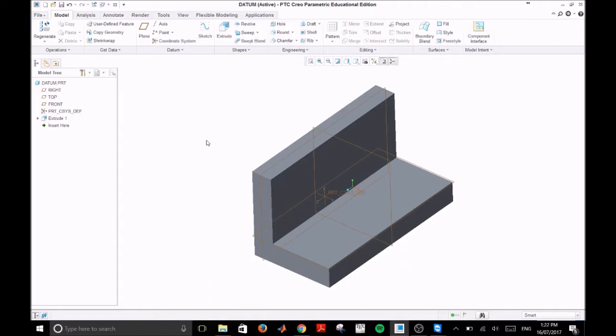By now, you've probably practiced a few extrusions and appreciate the usefulness of datum planes. For example, in this object, we have a right, a top, and a front datum plane, off which our feature has been extruded symmetrically. Symmetry is generally very good practice, and parts or features that are symmetrical should be aligned on datum planes appropriately.